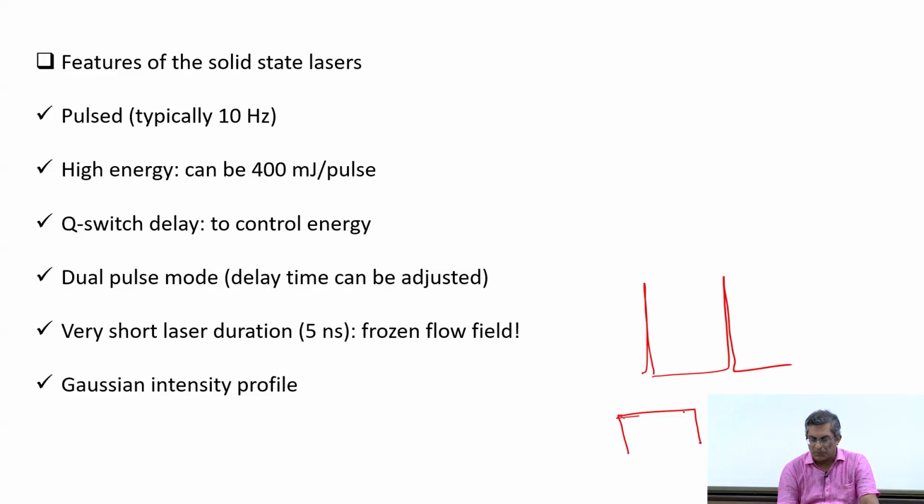Even if the camera exposure time or shutter speed is such that the shutter opens for a longer time, you only visualize the flow when there is a laser shot. You won't be able to see anything without a laser, because the particles won't scatter light usually. If you put the particles, let us say here in this room, you won't be able to see or image them properly. They will be visible only when you have a laser shot.